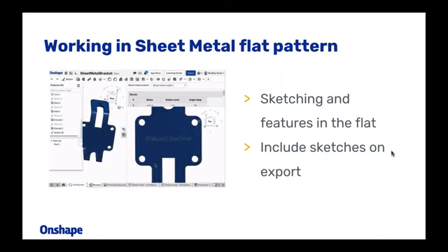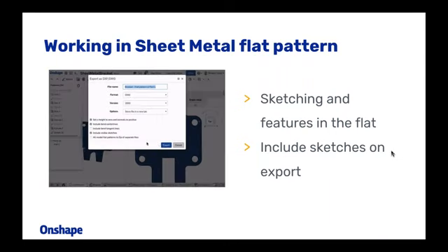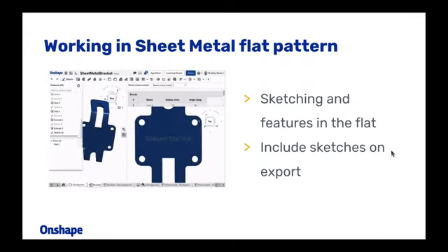Along with this, we also are now able to include sketches when you actually export your flat pattern as DXF or DWG files. So that'll be very useful when you get to your laser machine or engraving machine and need to either cut in a certain name or serial number instead of cutting all the way through.